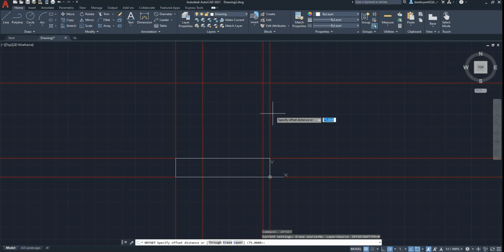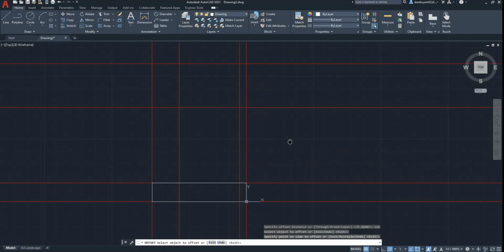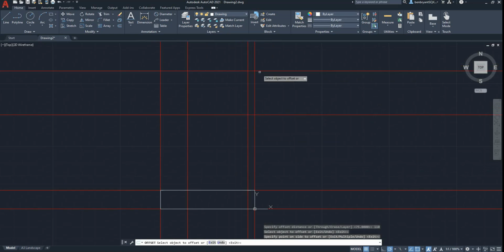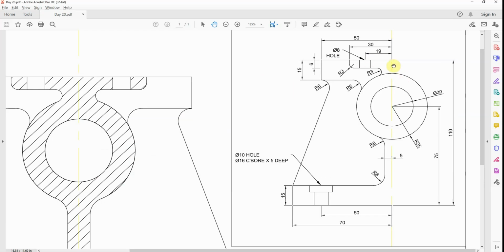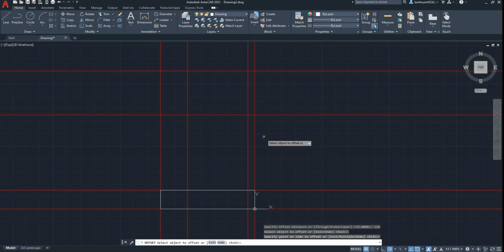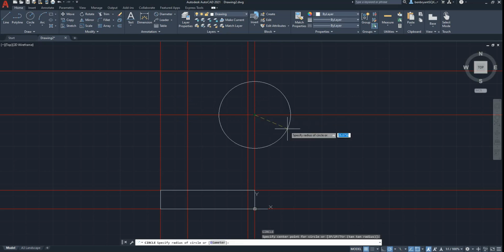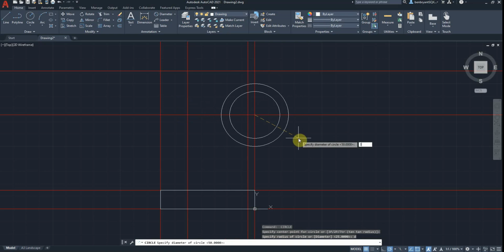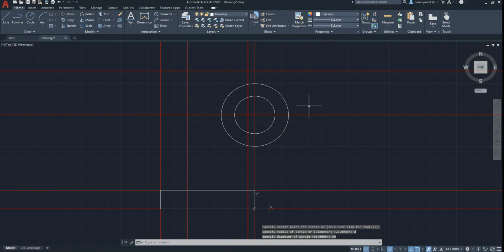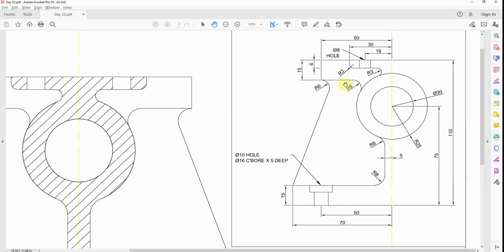Before I come into circles, I'm just going to do 110, that'll give me the top part of my view. So that's now up here. So I've got centre circles, the top of my shape, which is now all the way up here. So I'm going to put my two circles. I've got diameter 30, radius of 25. So circle tool, choosing that point, 25, same point again. Okay, D for diameter 30. That's put that bit in there as well. So radius of 25, so essentially diameter 50, and diameter 30 in there.